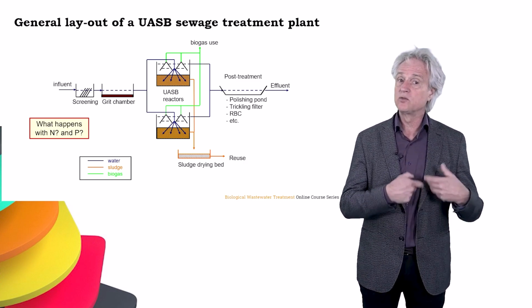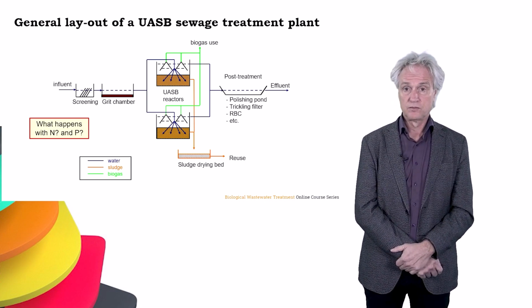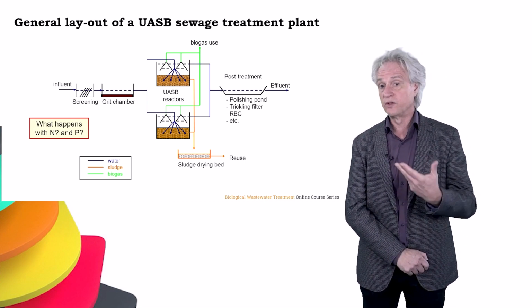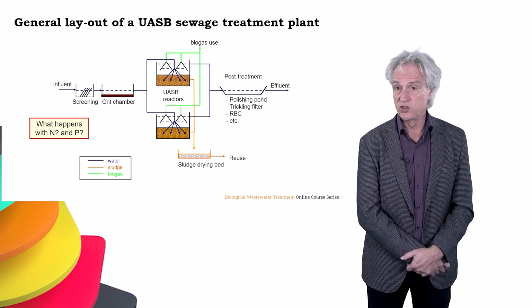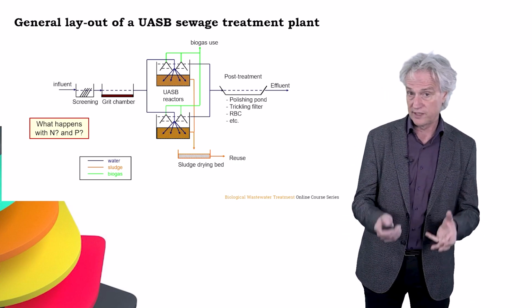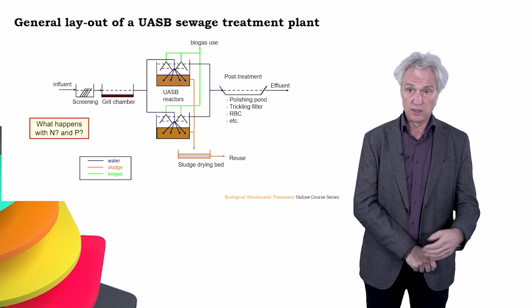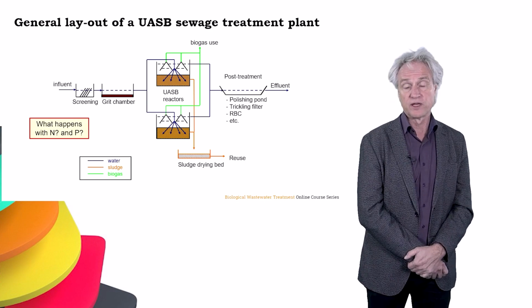This means if you would like to address it, it has to be addressed in a post-treatment system. Alternatively, if you do consider the effluent for irrigation purposes, then N and P could be of interest for fertigation. These are valuable nutrients and could be used for irrigation purposes.